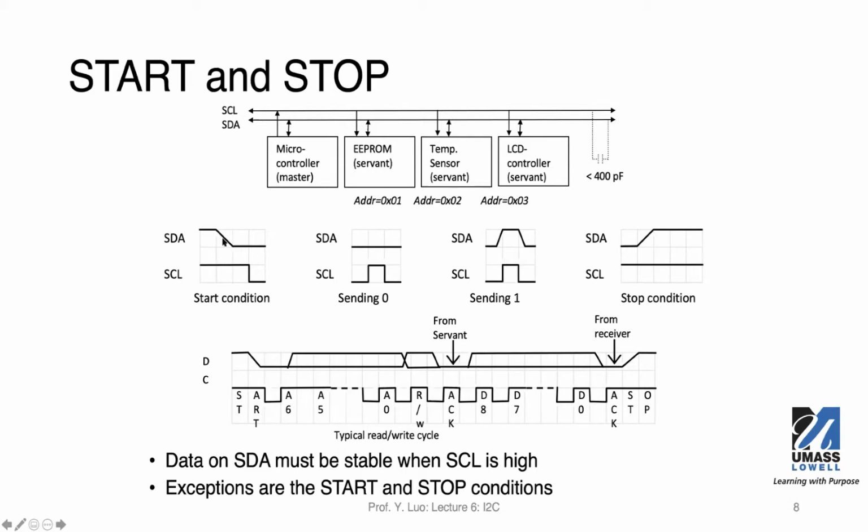This is an indication that the master is going to start the communication. So this is what we call the start condition. Again, the start condition begins when both of the wires are high, which means the bus is idle, and the master drives the SDA line to low, indicating it's going to start the transfer.